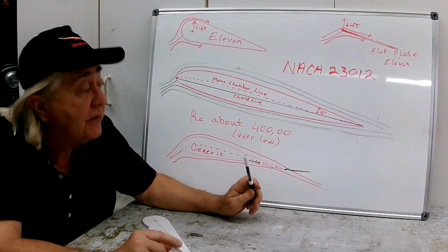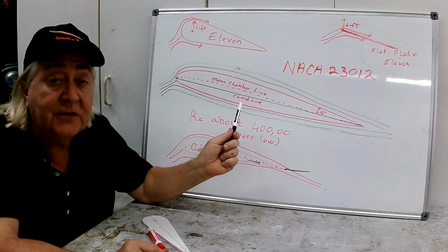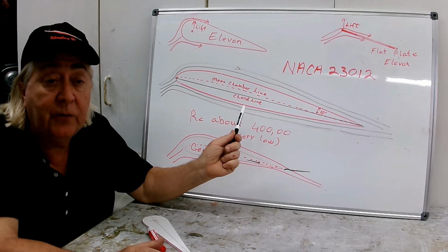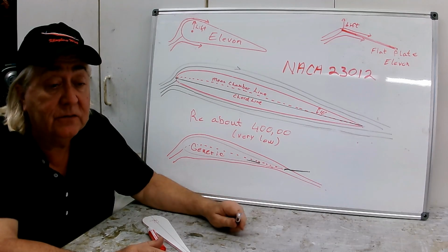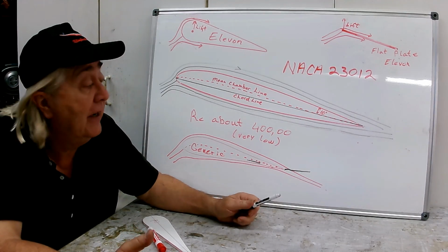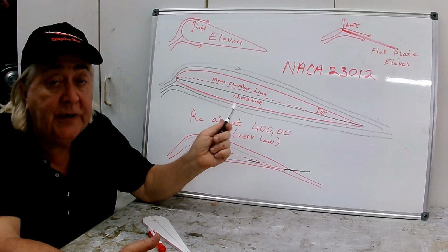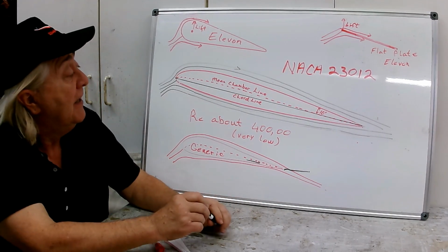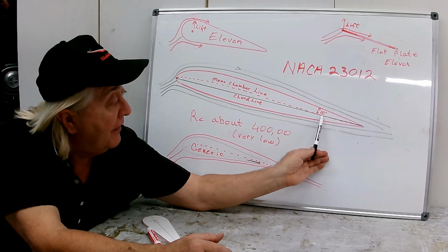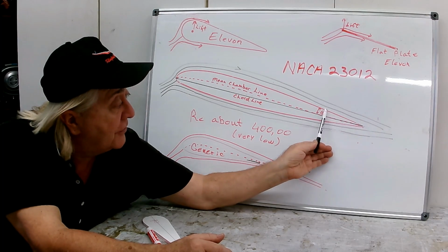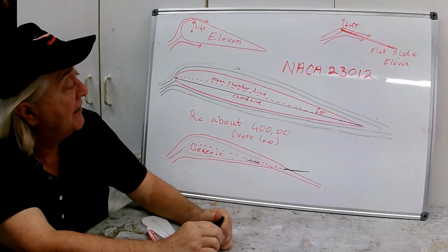And as a plus, cool airfoil, it can generate pretty high CL. And that's something that's often missing from a lot of flying wing airfoils. Symmetrical sections and so forth don't pull a lot of CL. And of course, that's what we want. We're flying a glider, we want high L over D. So it has the nice pitching moment curve and can pull a pretty darn high CL max. So a great airfoil. Now, at the trailing edge, I want to note here that the angle between the chord line and the surface is about 10 degrees. And that's going to be an important number here in a couple of minutes as I talk about this.